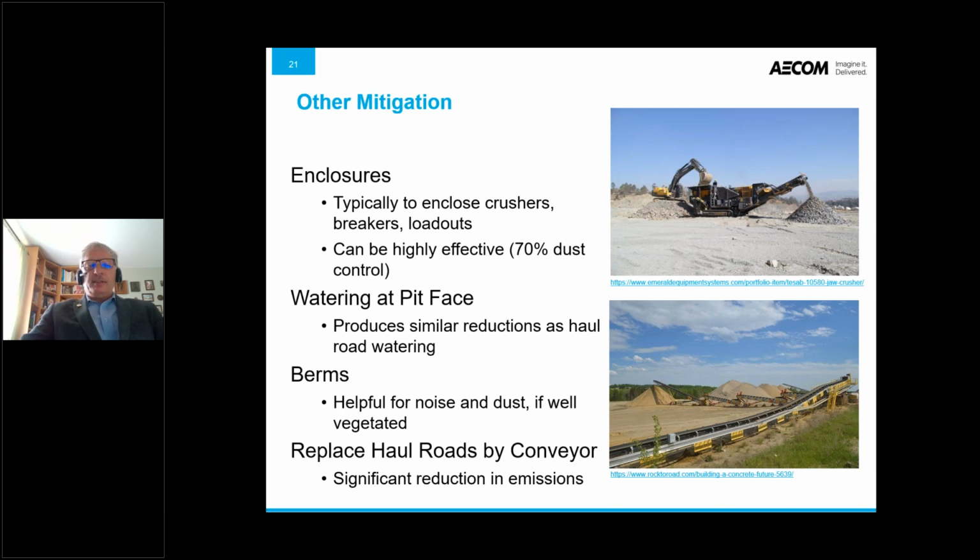It's proven that the kidney shape, which is made by stackers spreading material over some area, is much better, especially if you arrange it so that one stockpile shelters another, so the wind is not going to emit that much from the second stockpile because it's sheltered. Those are simple things which, if you know them, you can change your operation and decrease emissions.